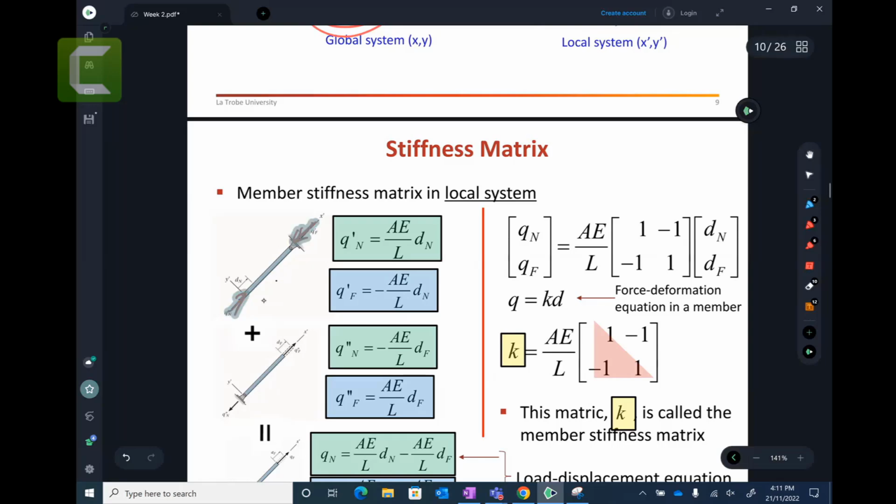So that is the force qf that is sitting here. Now, what is the logic for this end? You remember the near node and far node. Every node has a definition, meaning it can be classified as a near node or a far node. Who is going to tell us? This location vector is going to tell us. That arrow is telling me that the tail side is the near node and the head side is the far node. So that is qn and qf. I hope you understand that.